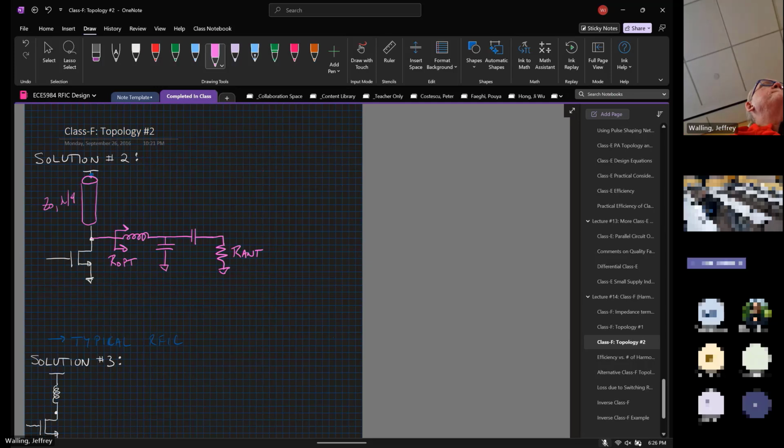And now, what's the impedance at the drain at the fundamental frequency? Just the amount of the transistor, because that would be an open circuit. Yeah, it's R opt in parallel with an open circuit, which is R opt, right? So at the fundamental, this works.